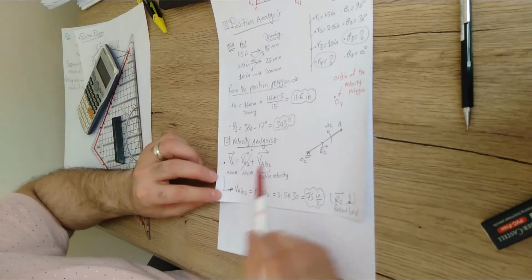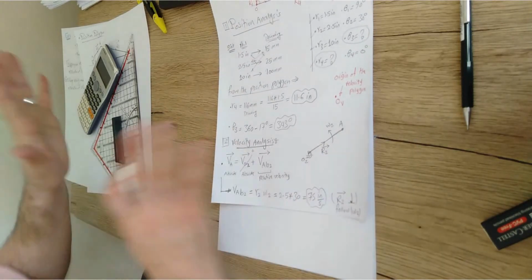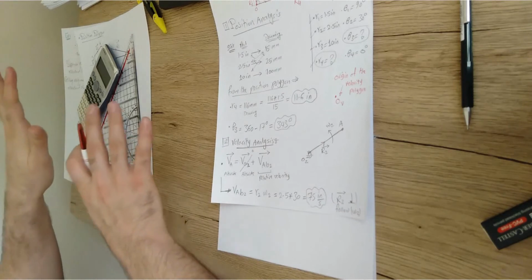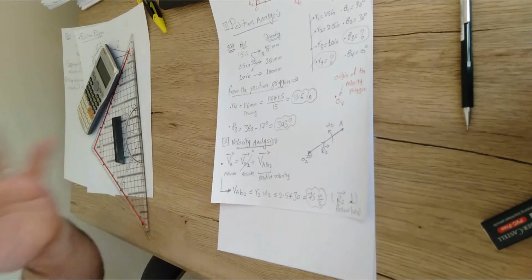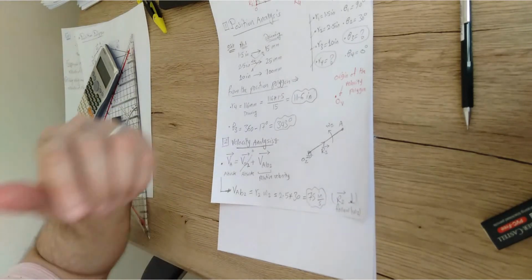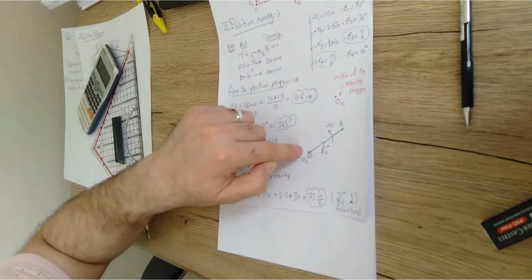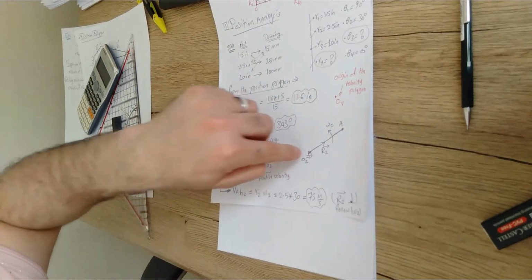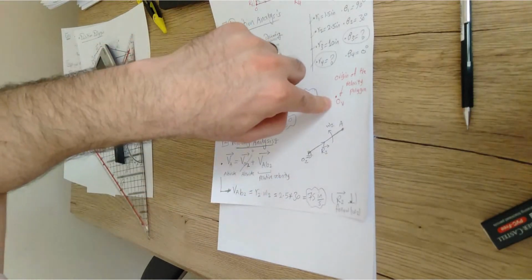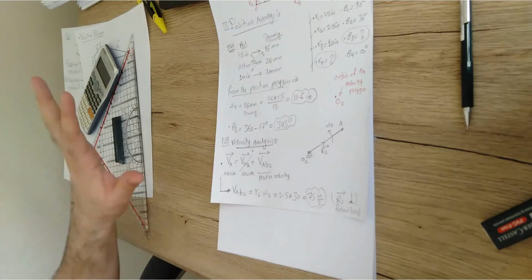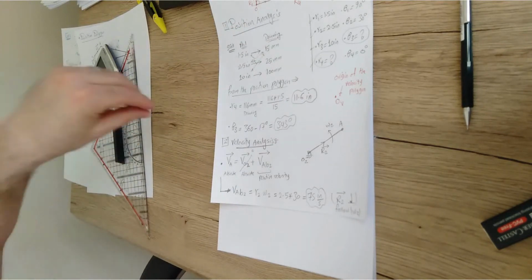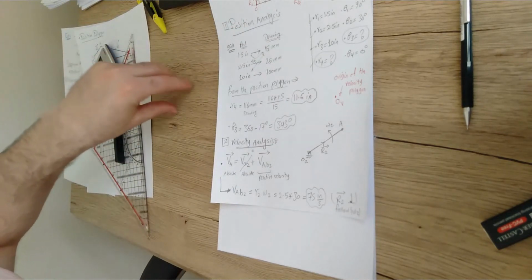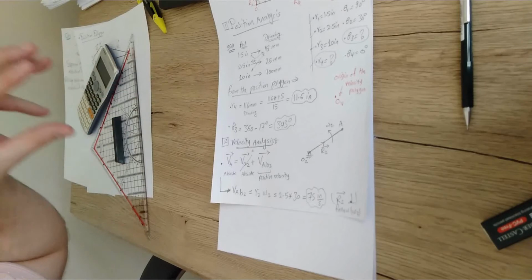So what does it mean? Here we didn't draw anything in the velocity diagram yet, right? So which point do we already have? The first point that we have is point O2, because O2 will be considered as OV. The first thing you're going to do when we start drawing is define the point OV. Again, this is the origin point of the velocity polygon.